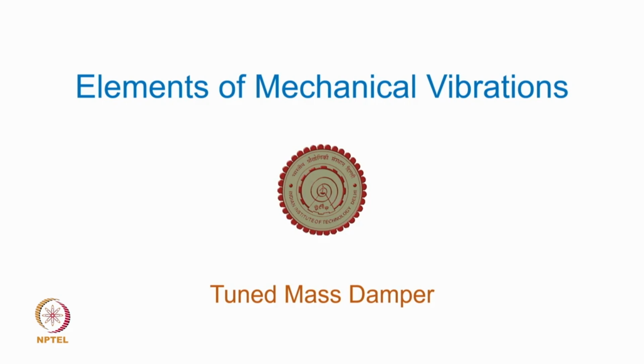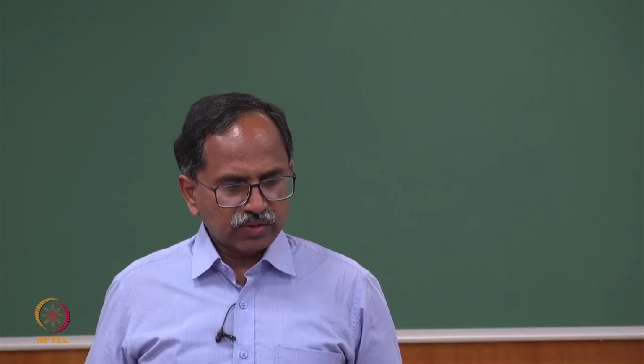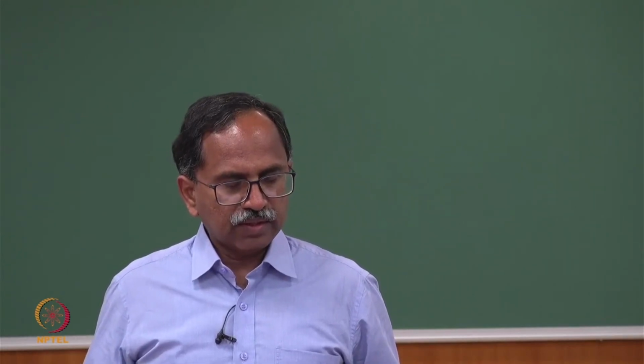But there were issues that if the operating conditions fluctuate a lot, then instead of a 0 vibration amplitude, we can actually encounter large amplitudes of vibration, because the two new natural frequencies are not widely separated. So, there are these issues of an undamped vibration absorber. So, in today's lecture we try to get around this limitation by introducing a damping element in the absorber design.